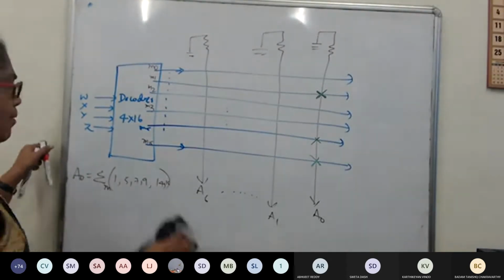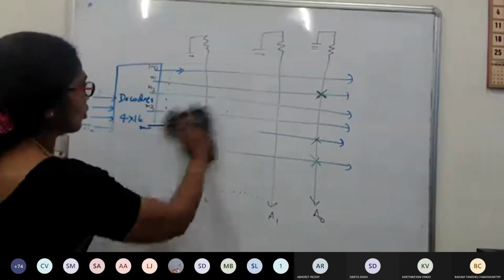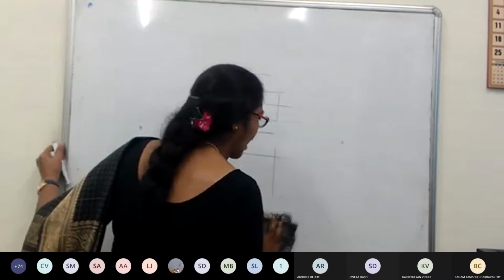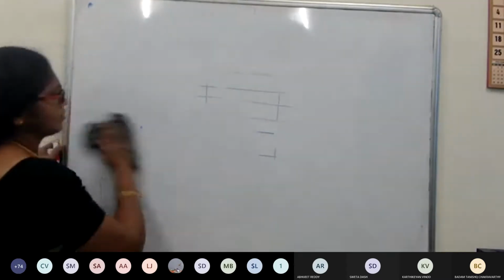So this is just an example of how to design a ROM. Given the truth table, we can prepare a program, a mask, for the requirement. So A0 to A4 only are shown; you can add 5, 6, everything in that. I need everybody to learn that. There's nothing much to learn. You need a decoder and word lines to attach to it.